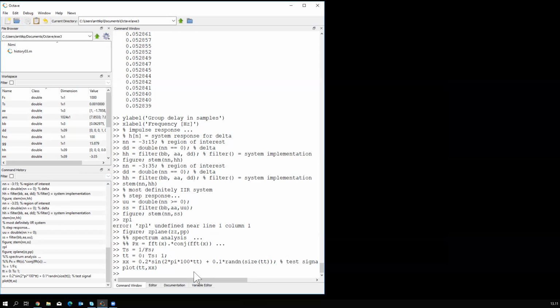We can calculate the power spectrum. This is the complex power spectrum. We calculate the FFT. Okay, not yet. I will calculate this so that it's actually calculating the first 512 values. FFT actually likes 2 to the power of n samples.